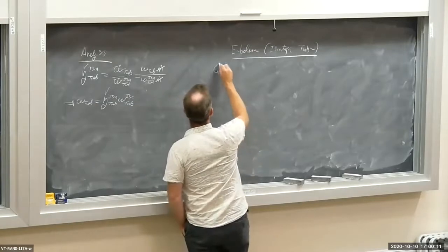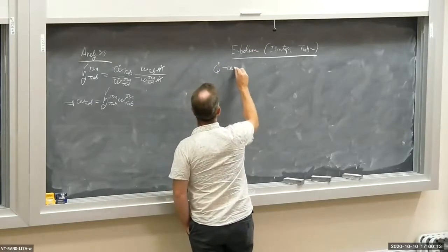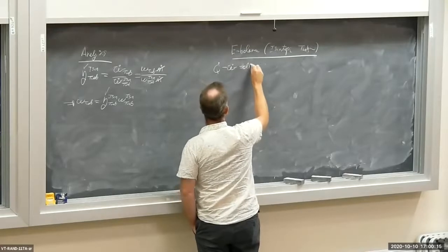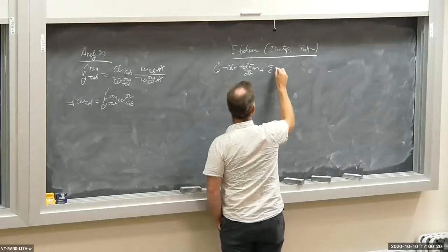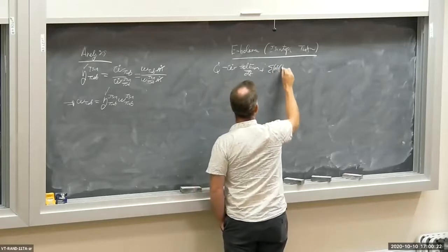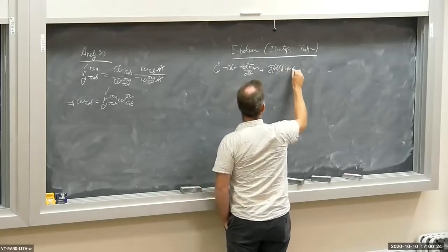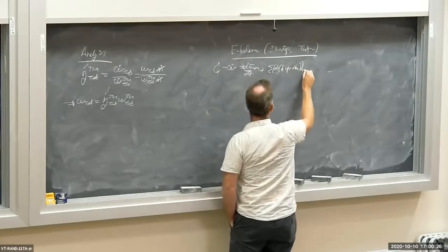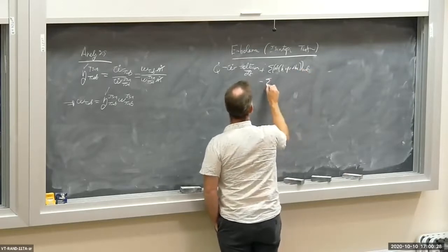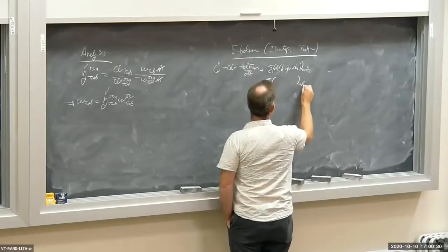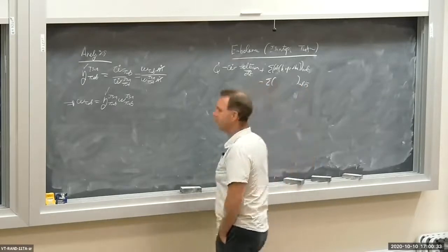We got Q dot minus W dot is equal to dE CV dt plus the sum of m dot (h plus PE plus KE) summed over all outlets. And then I got the same thing summed over all inlets, okay?